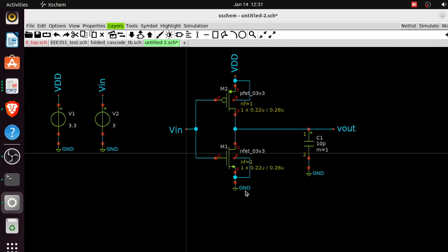Most times we want to do that to get more voltage. So if you have only 2.5 volts and you want up to 5, and maybe a single 5 volt supply is not available, you can use 2.5 for the VDD and use minus 2.5 for the VSS. But for this case the VSS is ground, just the zero reference.